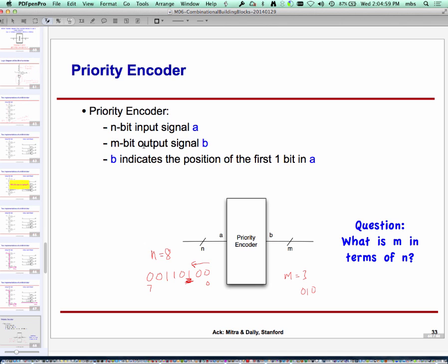So for example, let's take too hot. For too hot to be lit, of course, the temperature has to be greater than or equal to the set point, but the additional clause is that both temperature and set point have to be valid. That is, they cannot be 0, 0, 0. So you have to translate this into the different conditions and create an expression.